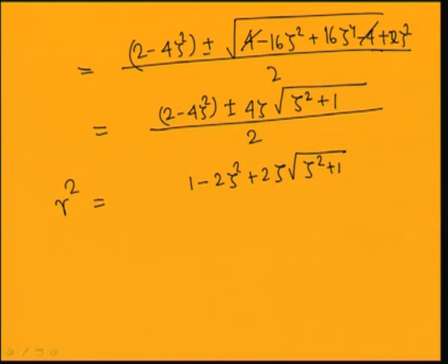So, you can write this r square equal to 1 plus 2 zeta. You are neglecting this term with respect to this, so this becomes 1, so it becomes 1 plus minus 2 zeta. So you will have 2 values. So you are getting r square equal to 1 plus minus 2 zeta, where r equal to omega by omega n. So this gives 2 frequencies, one corresponding to omega 1 and the other to omega 2.